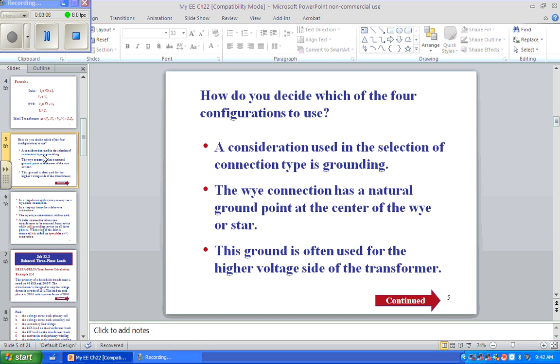If it's shorting to ground, it will just arc weld. Okay? Don't be part of that arc welding circuit. You want to stay out of that system. All right, so a Y, in a lot of people's opinion, sometimes even mine, a Y is grounded and is somewhat safer because if the hot conductor hits the ground, if it creates a high enough current short to ground, it will trip the breaker because it does have a potential to ground.